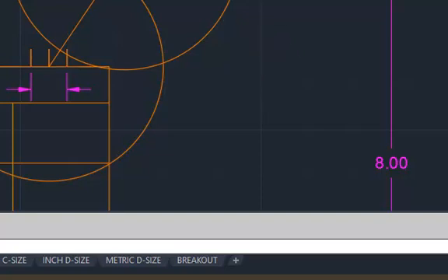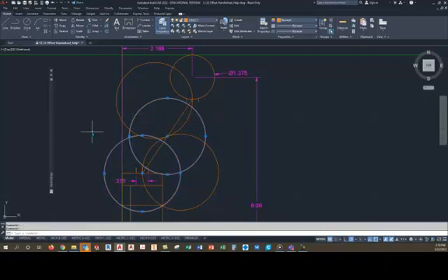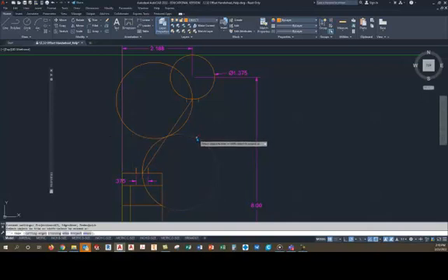Now I'm just going to be lazy and copy this circle down here to this spot. And now I've got a whole bunch of circles and it looks like crap, but that's okay. I'm going to get rid of the ones I don't need, like so. Now, I'm not a fan of the new trim command, and that's just the way it is. But if we go to trim and we get rid of some things that we don't need, it uses everything for a trim.